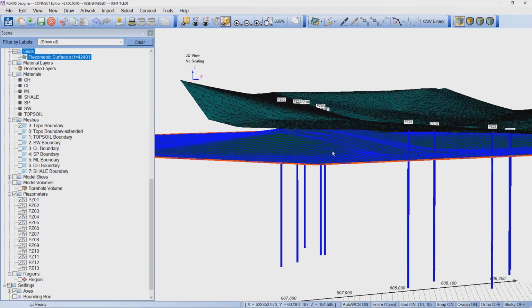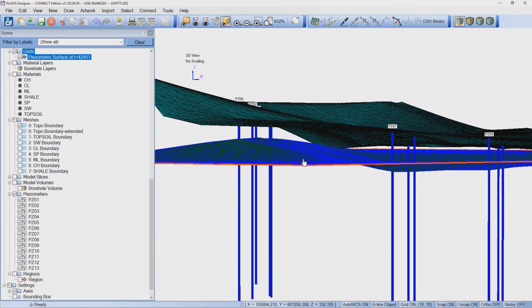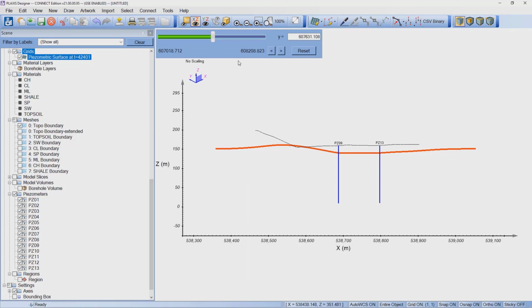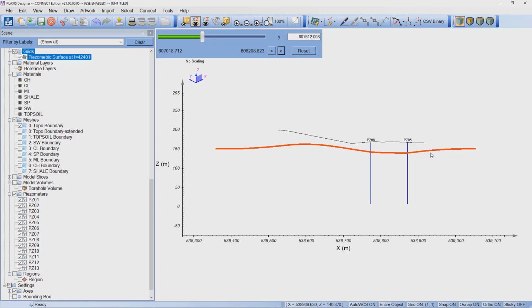You see that the water level was generated as a grid, okay, as you can see here. So if we change to the SC view, we can see the position of the piezometric readings, as a surface, using this specific interpolation method, along with the changes in the top surface mesh.